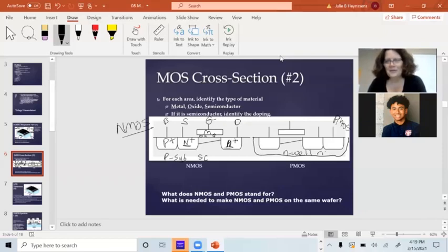The circuits that use both PMOS and NMOS transistors are called CMOS, which is complementary MOS. But there are two distinct types of transistors within here. Same thing over here. I've got the gate. I've got the body. The body is going to be tied to the N well.